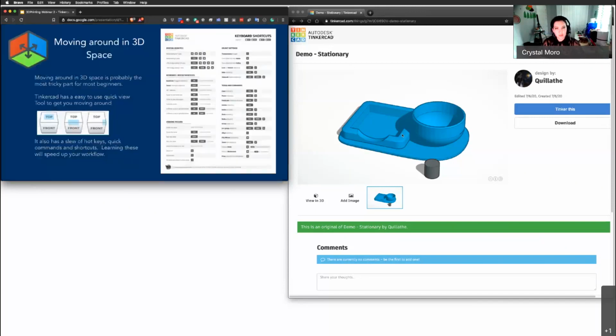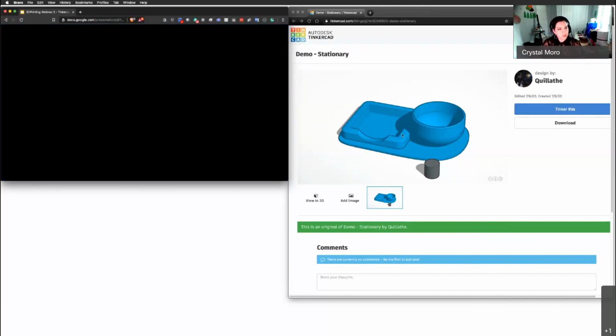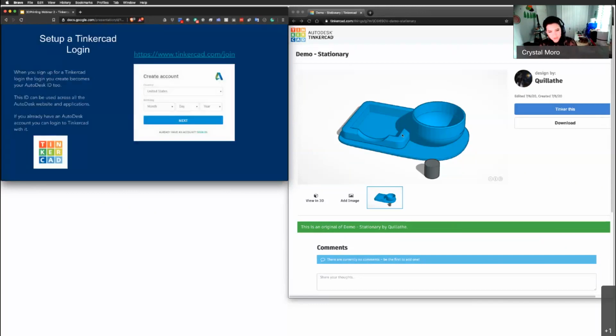So I guess a little bit about me. Let me go back in case you need the information. I have a bachelor's degree in computer animation and media arts. So I've done both block modeling, which is what I'll be doing today in Tinkercad, and then I've also done NURBS, or what's called surface modeling. And the difference between the two types of modeling is block modeling is obviously taking blocks, cutting holes in them, merging them together, or dividing them up and then extruding parts depending on the application you're using. Whereas surface or NURBS modeling is taking points on like a plane and sculpting that.